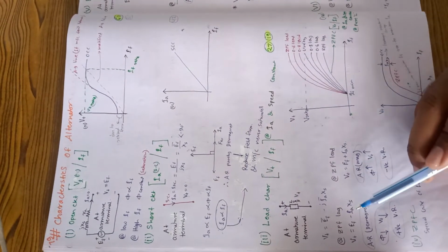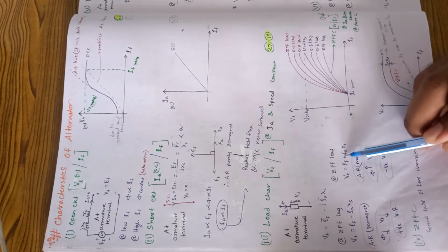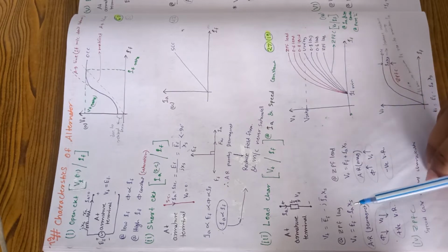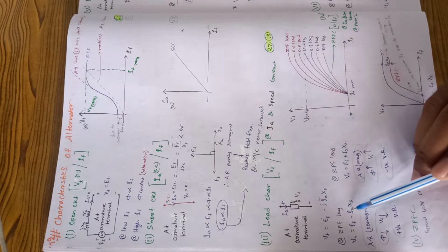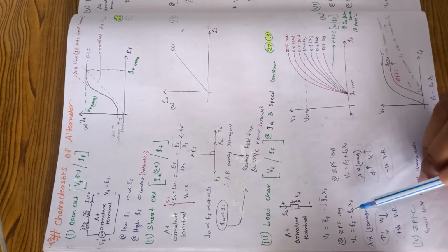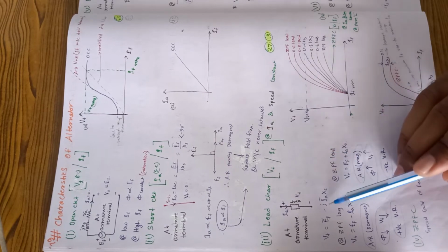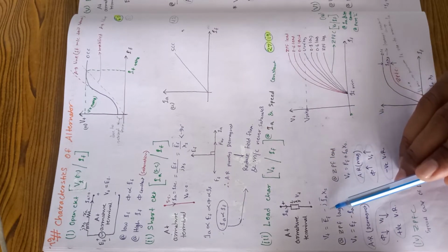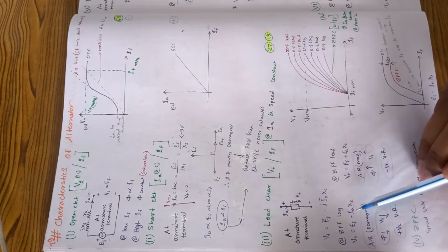You must be wondering why there is a minus here and a plus here in the case of leading. In the case of lagging, the current is at angle minus 90. Lagging means minus 90, and it is ZPFC, so minus 90. Minus 90 means minus j. So minus j into minus j gives j square, which is minus, so ultimately we get minus Ia Xs.